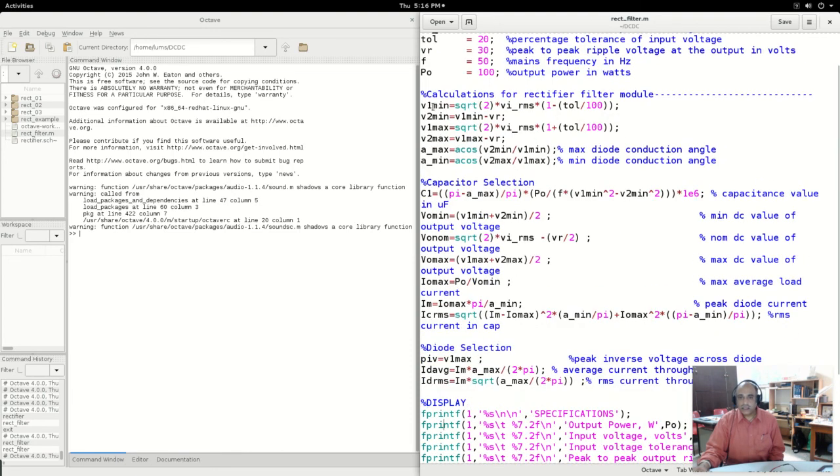And the calculations, you first try to calculate what is the minimum value and the maximum value of the peaks, so that you can get the worst case condition. Go through these equations just like we discussed, but I have now used the tolerance values also. Similarly, you will get two values for alpha min, alpha max.